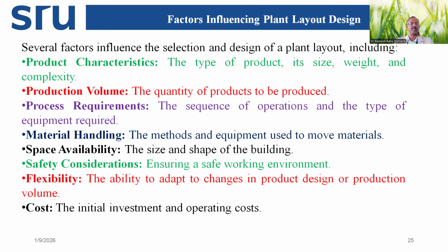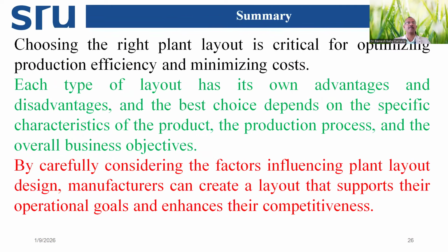Flexibility. So the ability to adapt to changes in product design or production. Today we are making some X design product. Maybe after 1 or 2 years, the market requirements may change. Maybe we need to incorporate better design features in our product. At that time, the processes may change. We need to modify our layout. So first, layout design should facilitate future changes, re-layouts. And the cost, what are the initial investment and operating costs need to be known to decide the plant layout design. Now let me summarize this session.